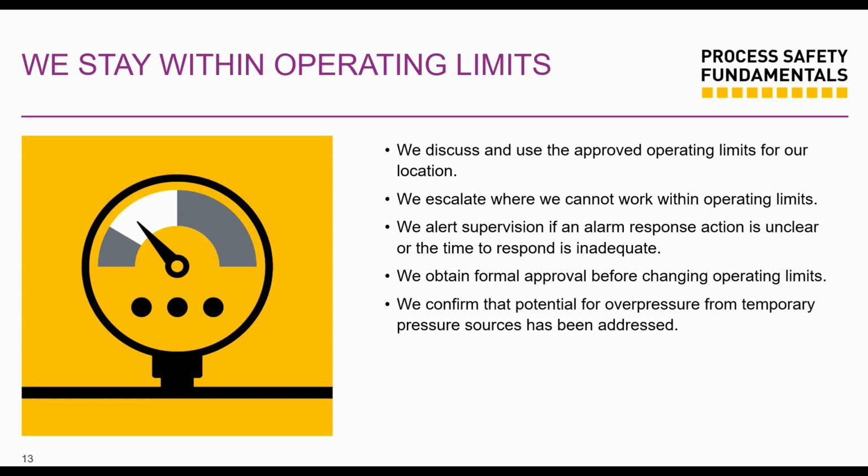You're increasing that heater temperature, and then the tubes in the heater fail, and you have to shut down. You're doing this because you want to produce more, but you end up shutting down your site for a couple of days just to fix a tube rupture. So these are all about staying within operating limits.